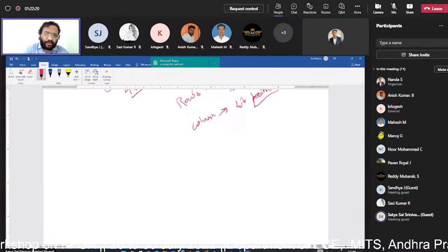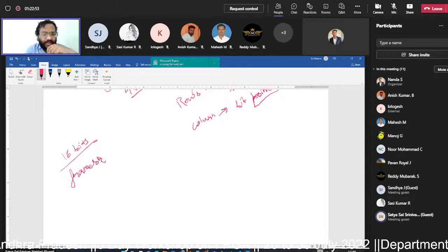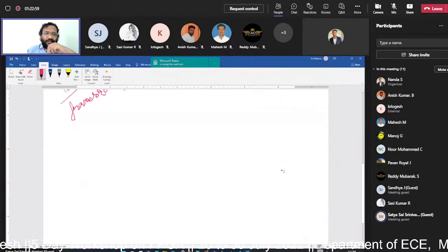Our interest is to store the frame samples, or the signal samples, from the text file, and from that we need to read each and every sample and give it to the module. Our samples are all 16 bit wide. How many samples are there? In our current example, we have taken a frame size of 8. That means we need to store at least 8 samples.